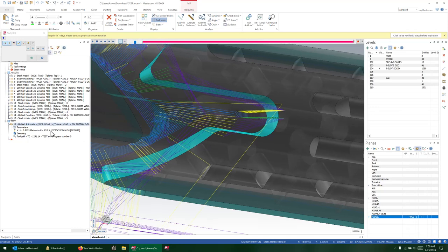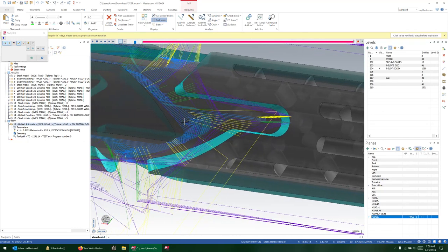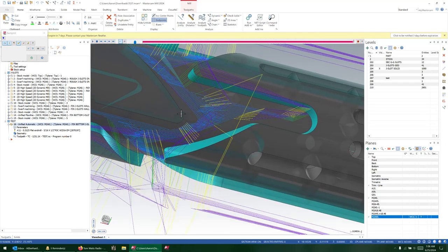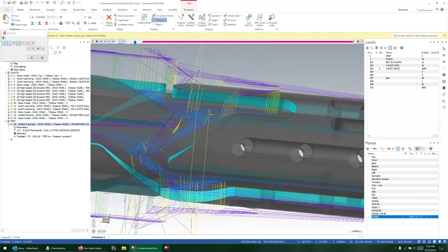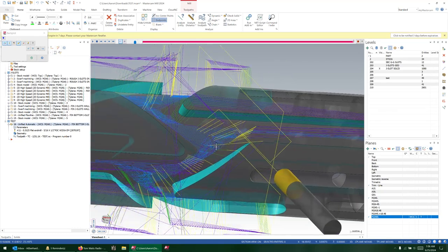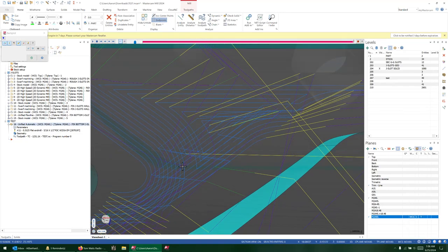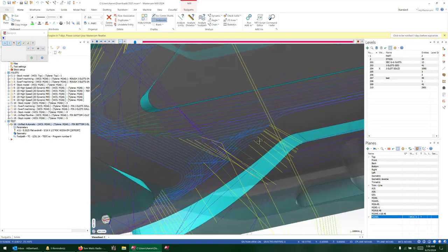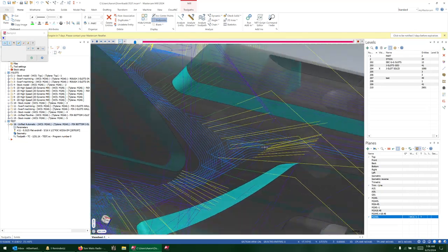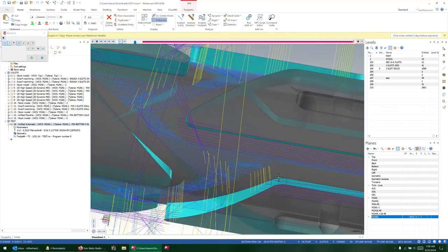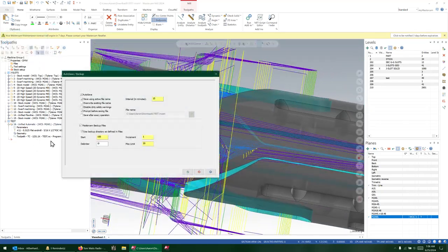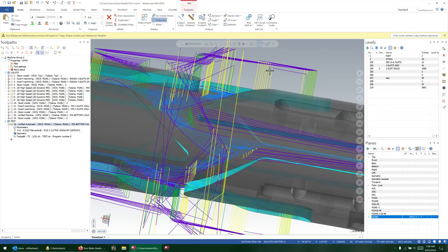Now, he has a setup here with a 5/16 end mill, so 0.3125, and this is running into some issues here. There's some noise in the toolpath down on the bottom. The pattern itself we don't necessarily like, and of course there's a bunch of retracts and other things where it's kind of gouging into the walls. Now, there's a lot of options set, and I don't want to go through and deconstruct every step that he took to get here. So I'm going to start with a clean, unified toolpath just to put something on here.